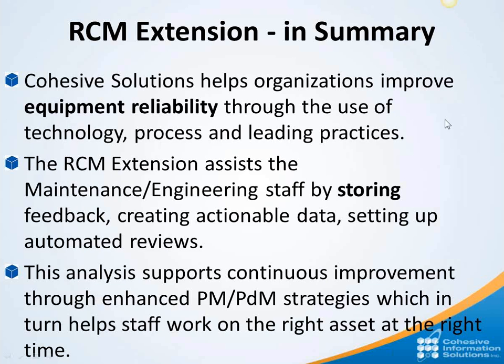In order to do the RCM analysis, you need the maintenance histories and failure codes and assets and locations that exist in Maximo to develop your maintenance strategies, which then get implemented as PMs in Maximo. So we tried to set up foundational properties within Maximo to capture the data in one system so that we could automate those reviews and push the work items to the people that need them.